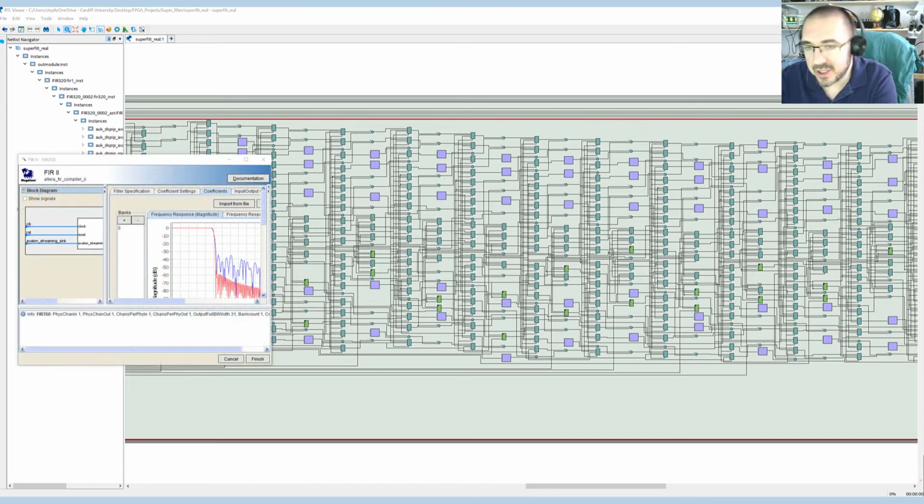So in summary, we managed to get up to a 320th order FIR digital filter. Now, of course, if you have a different device, different resources on the chip, then you'll be able to develop maybe a better filter than I have with my particular FPGA. And I'm quite curious about the way the compiler has traded off the use of the DSP blocks, which I guess are the preferred way to build a digital filter because it gives you those hardware multipliers, versus the logic elements.